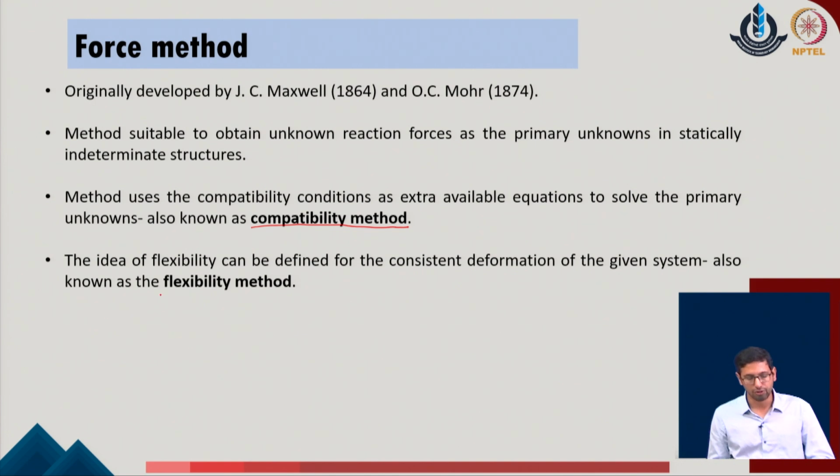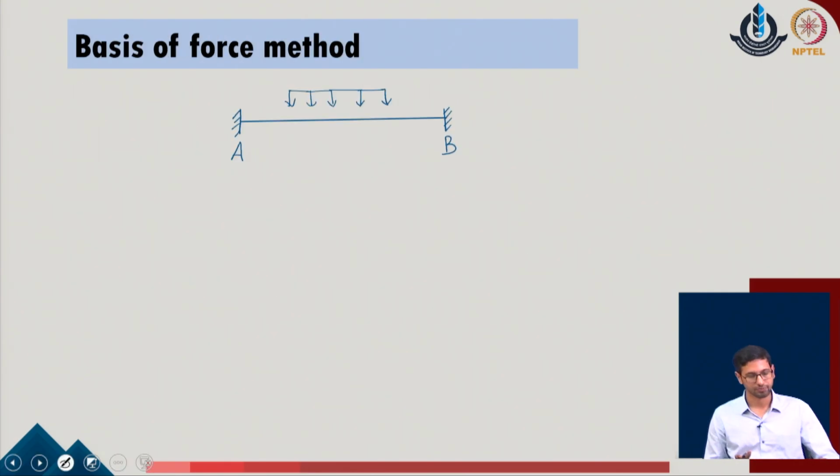So, as we introduce the definition of the displacements with respect to the unit load in the given problem, the method also introduces the flexibility coefficient, and that brings us to say that the method is also a flexibility method. So, in general, the force method, the compatibility method, or the flexibility method or approach, these are all similar names identified with the basic concept of identifying the reactive forces in the given system.